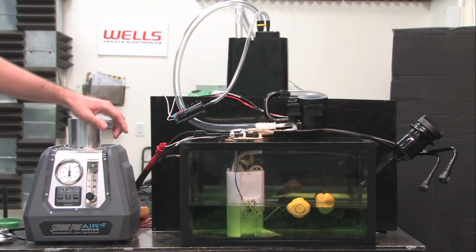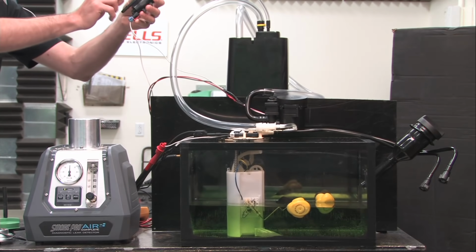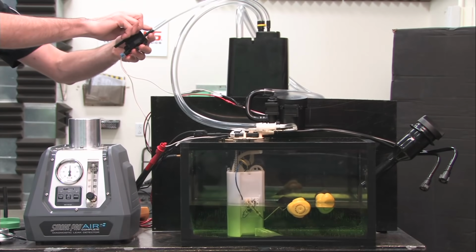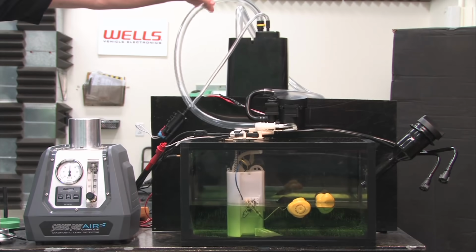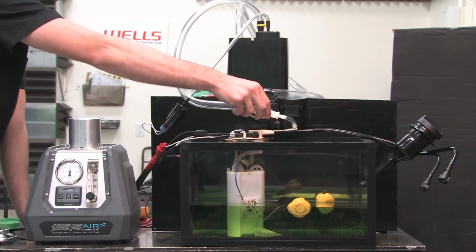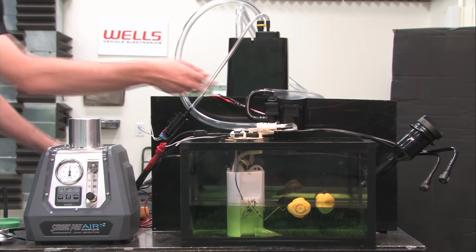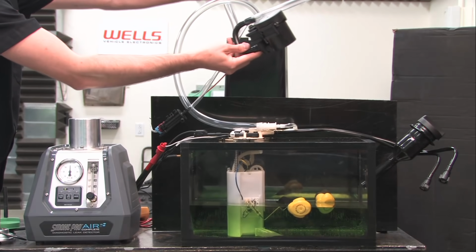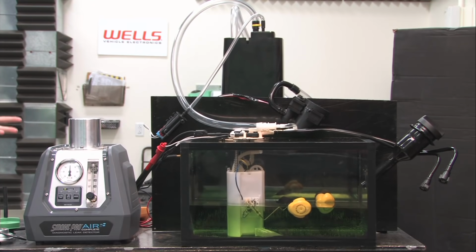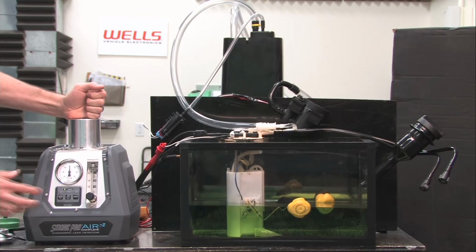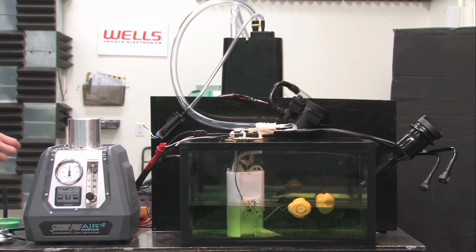Filler neck, gas cap sealed up. Purge solenoid, which is connected to a hose. Remember, this is going to be under the hood, connected to a hose back to our canister. And then we have another hose coming off the canister. This is the one that's going back to our fuel tank. When the vapors build up inside of the tank, they'll travel up to the canister. And then we also have our vent solenoid here, which is going to allow the system to breathe that fresh air. So I also have a smoke machine hooked up here, and I'm going to go ahead and power this thing up, maybe.